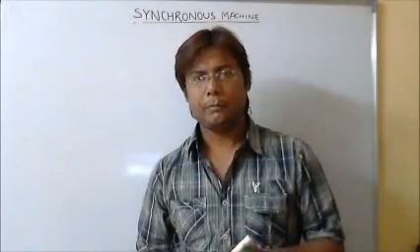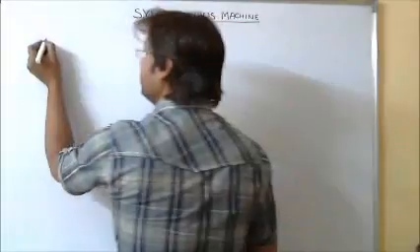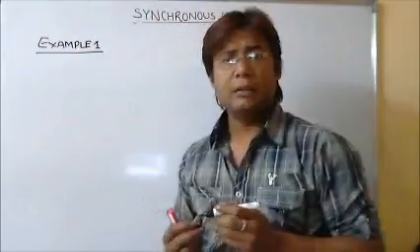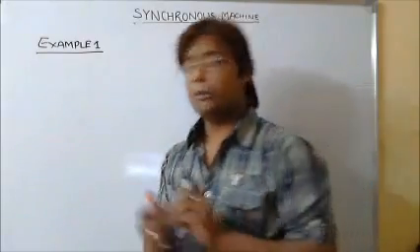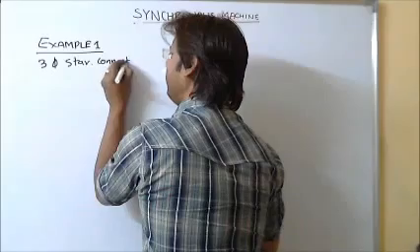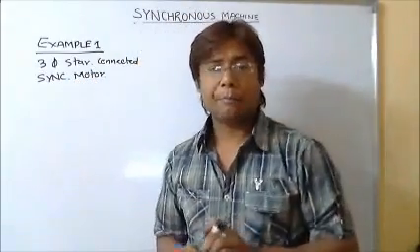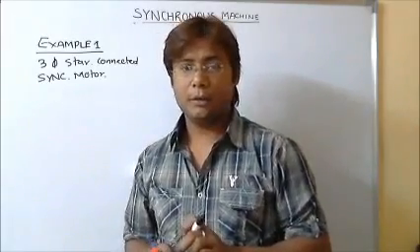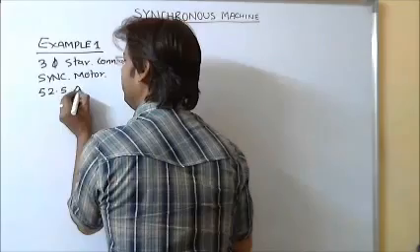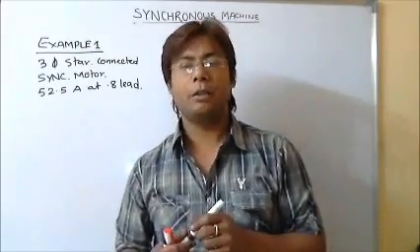We'll start with an example of a synchronous machine. The question is: a three-phase star connected 400 volt synchronous motor takes a load of 52.5 ampere at a power factor of 0.8 lead. We have to calculate the power supplied and induced EMF.